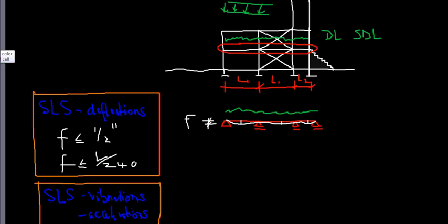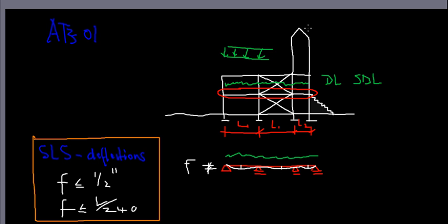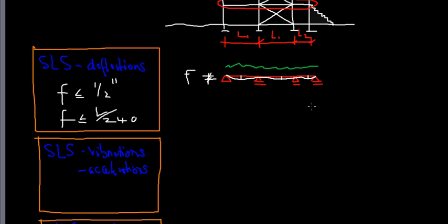I could have also chosen the same thing maybe on a vertical element. Say we have that tower here, and then this tower system might have a structural system simplified, which I'm drawing in a vertical way. And then if we had some wind loading coming from the side, which again say was like a linear load, we could also determine the deflection here and find the maximum of that wall, say.